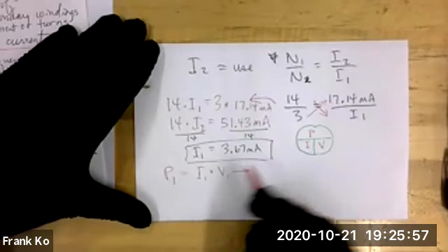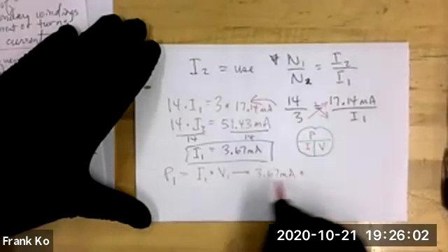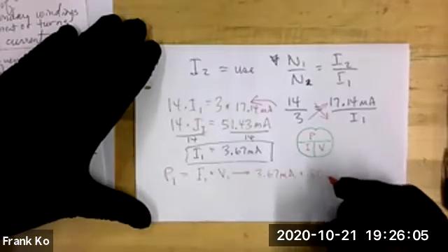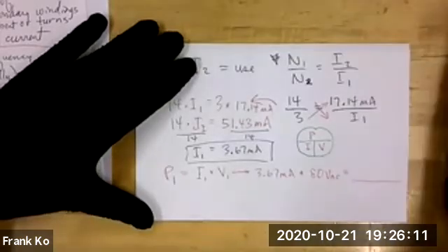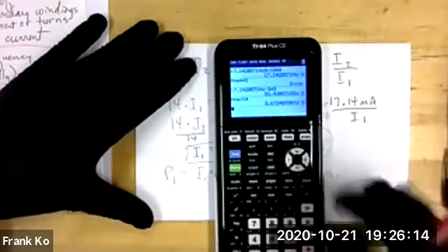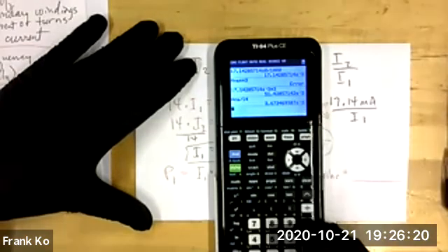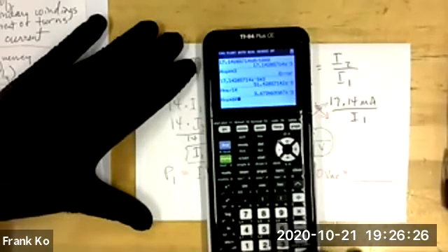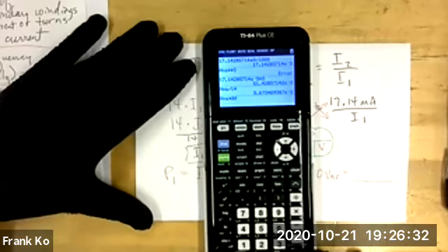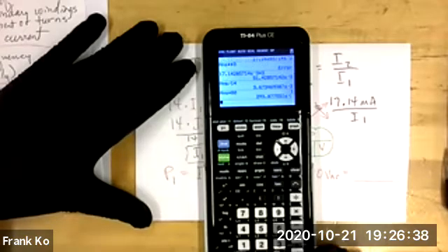And we just calculated current primary, so that's 3.67 milliamps, yes? And what's the voltage of the primary? It was originally given as 80 VAC, yes? Okay. Let's go ahead and make that calculation. So we have the current still on our calculator from before. And now multiply that by the 80. And before I hit enter, I would hopefully see that you will have hit enter. So I'm looking for that answer from Mr. Montalvo. What do you have? 293.6 milliwatts.